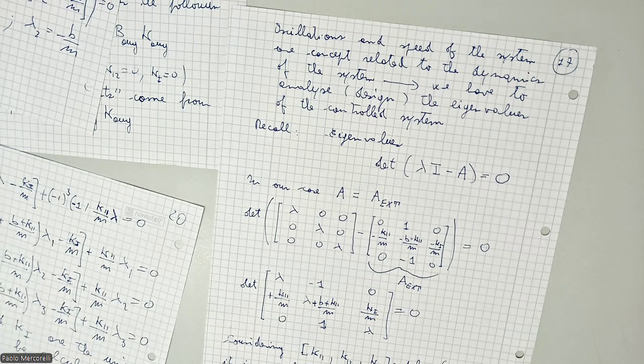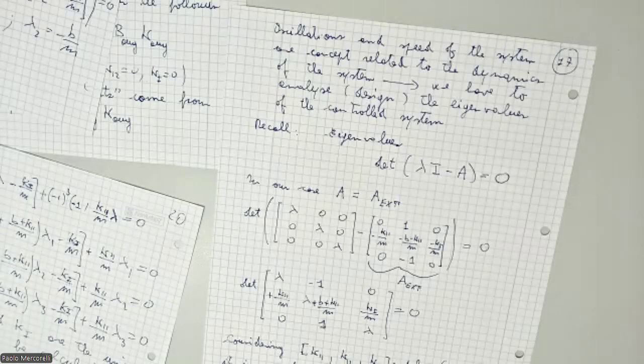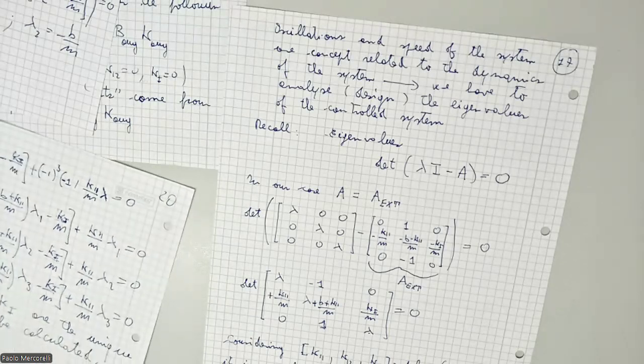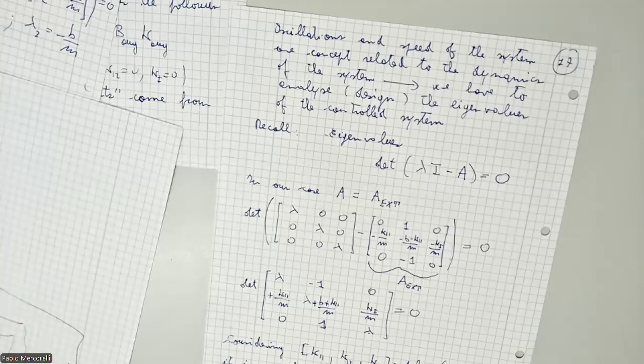And if I approximate the dominant dynamics with the largest real part, let me say, of the largest time constant, which is 1 divided by the absolute value of the smallest, excuse me, 1 divided by this smallest absolute value of the real part of lambda. I think I expressed correctly. We can now obtain the specification in terms of lambda. Of course, it's an approximation. But of course, using the simulation, we can eventually adjust.